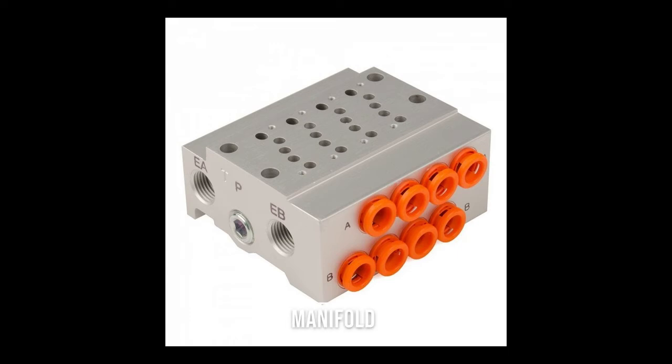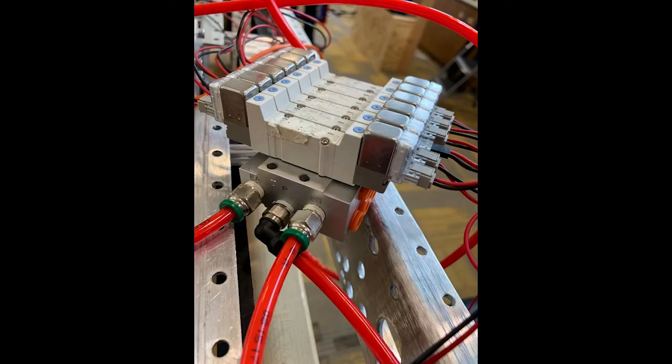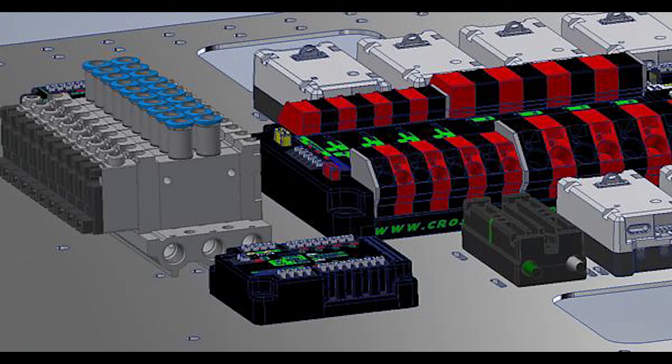Although something to note is that in our system we often use a manifold that the solenoids are mounted on top of. A manifold is just a base that we can put our solenoids on, and this base has all the holes that we would normally find in a solenoid built into the structure. This means that all we need to do to get this to work is have one tubing that connects and delivers air to the entire manifold, then place the solenoids on the slots that we want to use, and connect the corresponding holes to our pistons.